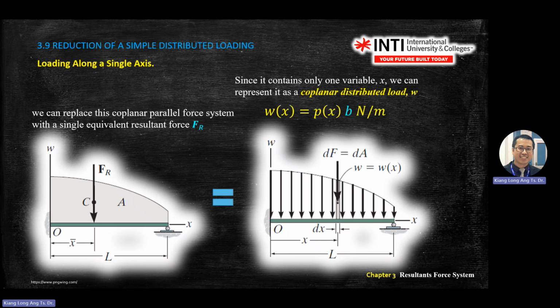So in summary, every time you see this, multiply by the length, then go and see the table. What is this shape? It can be a pyramid, it can be triangular. Don't worry, go and see the table. And important is to find this distance. Why? Because this distance will give you the moment. Then you continue with the steps that you learned just now.